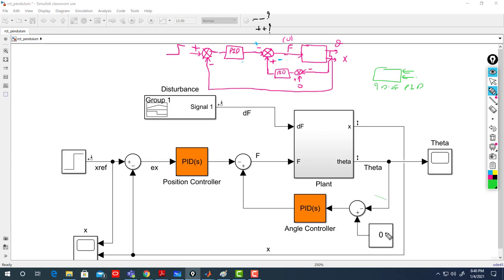So we can try here, instead of this, having a 2 degree of freedom PID, as we did in the previous session when we put it here, in a cascade or nested architecture. So now I'm keeping it the same as we did in the lab anyway, and this is still a feedback compensation as well. And in our previous session, we put a PID controller, but without the summation. We take it directly from here to here, and we had here a PD, remember? So we'll basically do the same now.